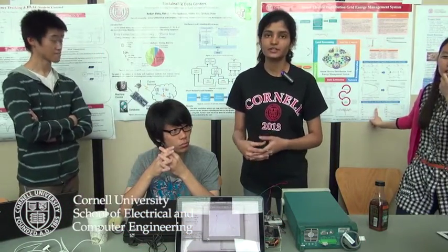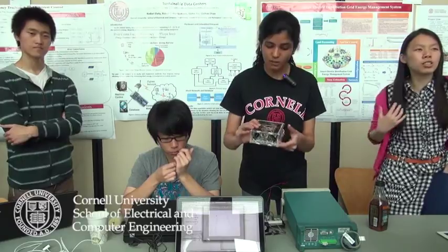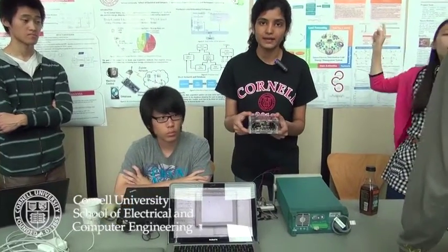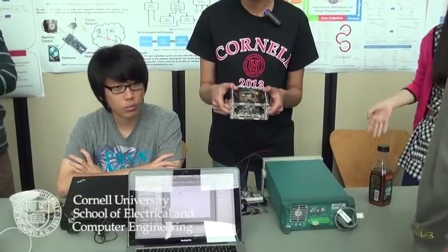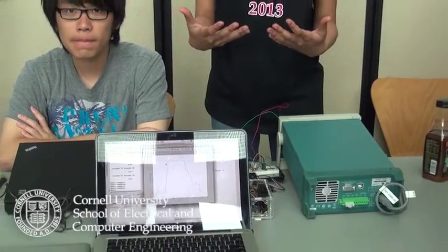Okay, so our project is basically sustainable data centers, where we're trying to reduce the energy consumption in data centers of Verizon. So we're building a small-scale data center in the lab, which simulates the heat output of a real-time data center. And this is going to be the small-scale version of the server racks. And we're building a data acquisition system which collects real-time data and sends it to a database which logs the data, and the user can take appropriate action depending upon the activity of the data center. So if the temperature is too high, then he can control the fan speed and accordingly take action so that they can reduce the energy consumption.